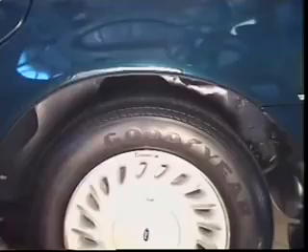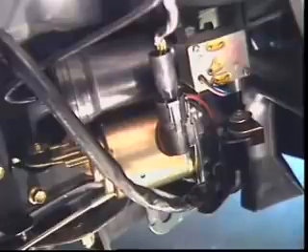The ECU is mounted to the crossmember over the rear axle, and a movable link connects it to a rear suspension member. As the vehicle is loaded, the normal suspension springs are compressed, which lowers the height of the vehicle. When the ignition is switched on, the ECU senses the lowered ride height and switches on the air compressor. Air is directed to the shock absorbers, causing the airbag around them to expand and raise the suspension to the normal trim height.